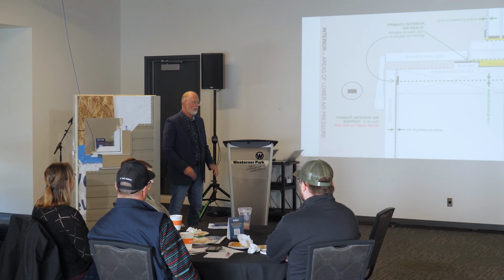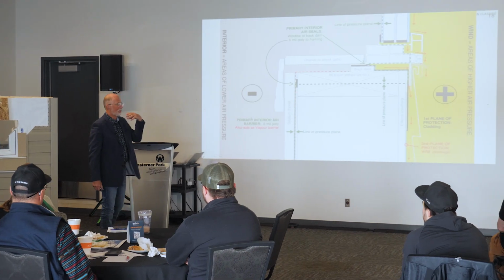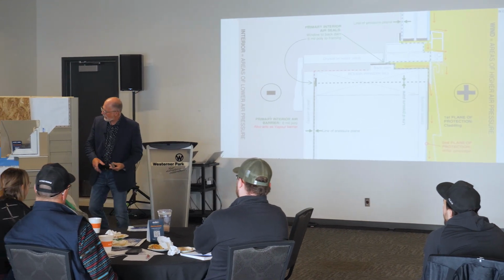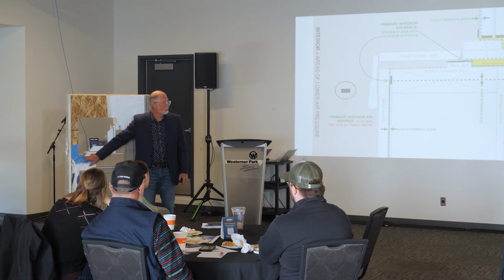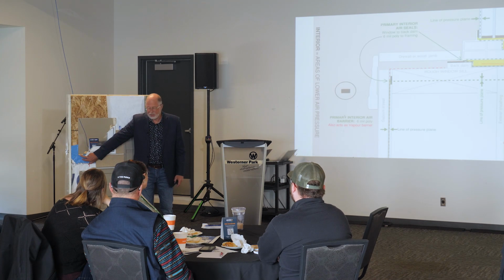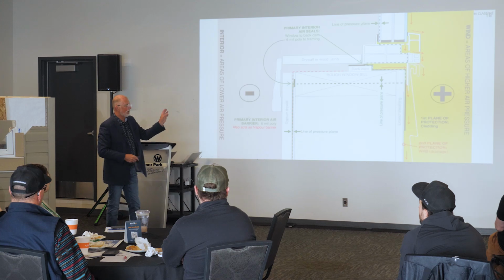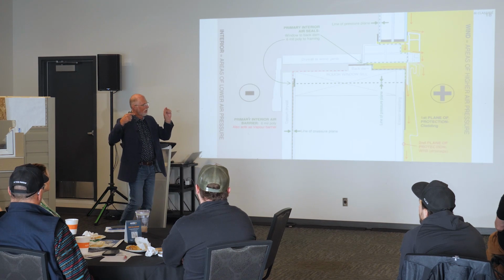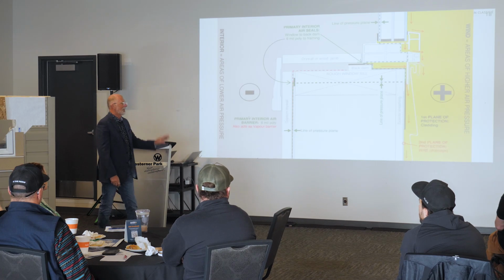Yeah, and they don't have to be very big. Now, one of the things we always recommend, as a building envelope specialist, I always told guys, on the face here, take a couple of pan screws and put them on before you install the window. Or if you're putting the shims on, let them be proud by a 16th or an 1/8 of an inch. There's all sorts of ways you can increase that drainage. But conversely, you don't want as big a space because the amount going in is going to increase. So that's the principle there.